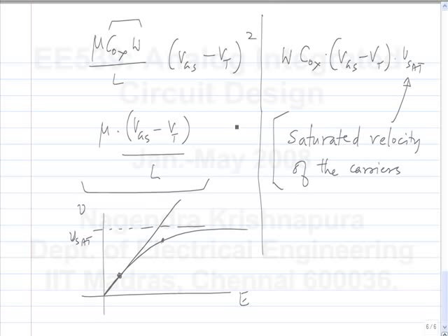So you can try and play with your simulator. If you plot this ID versus VDS for the minimum length transistor, you will not get a square law type of increment in drain current, but if you do it for, let's say, 10 times or 20 times the minimum length, you will probably get a more squarish law. Okay. We will see the implication of this.